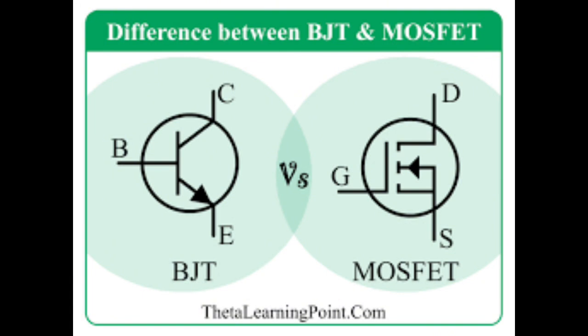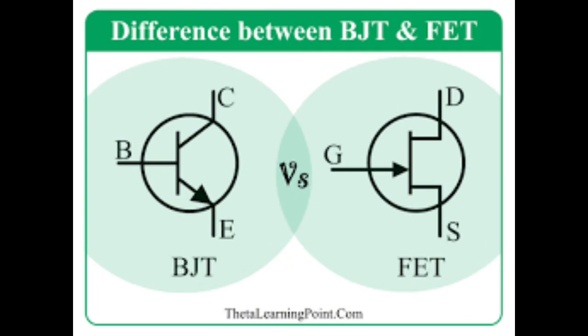For an NPN, the base-to-emitter and base-to-collector junctions will show a voltage drop of 0.7 volt for silicon when the positive probe is on the base and the negative probe is on the emitter or collector. For a PNP, the drop occurs when the negative probe is on the base and the positive probe is on the emitter or collector.